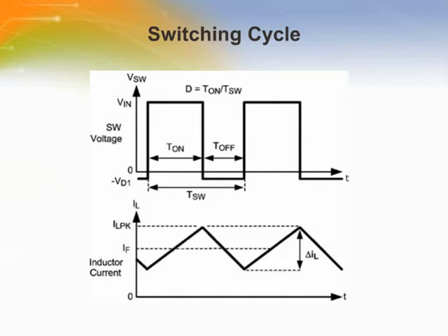The regulator loop adjusts the duty cycle D to maintain a constant output current IF through the LED by forcing the FB pin voltage to be equal to Vref, or 0.205 volts.